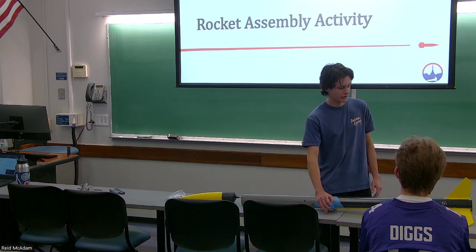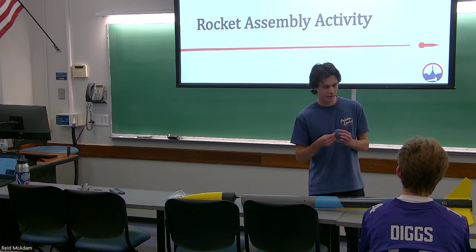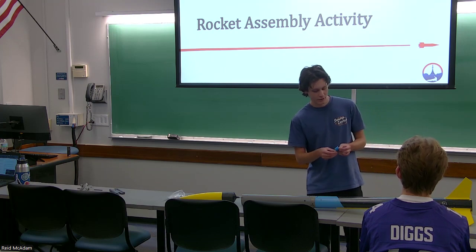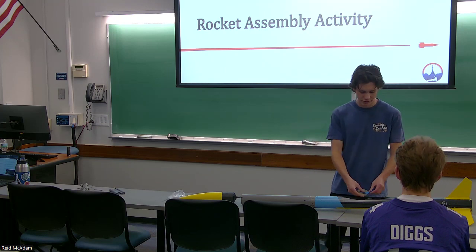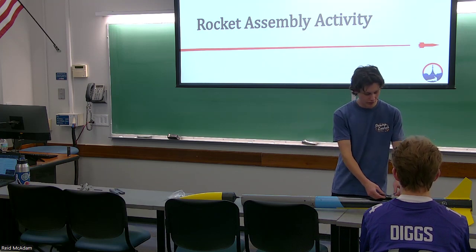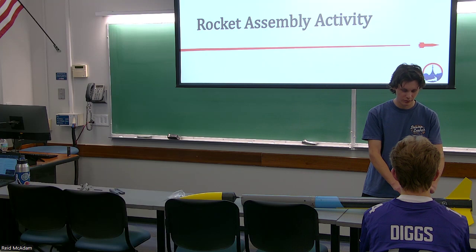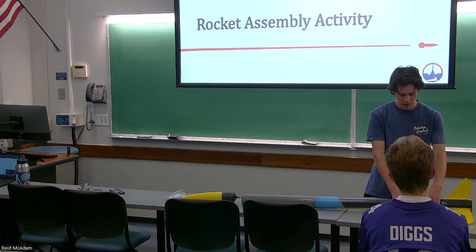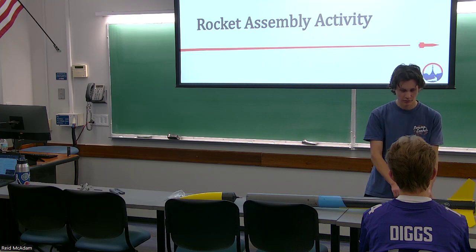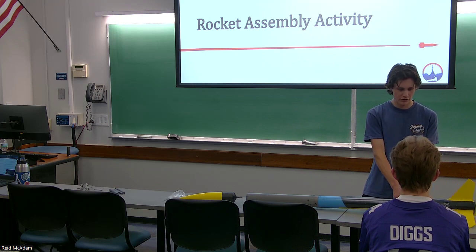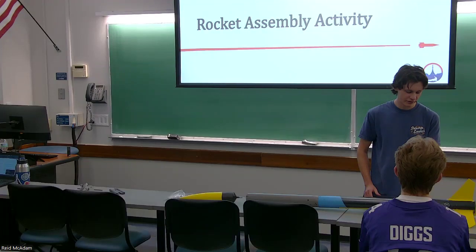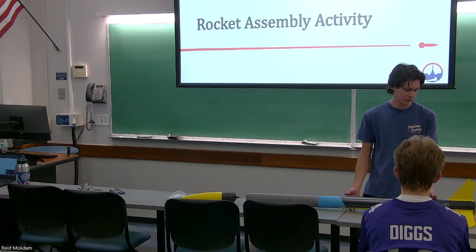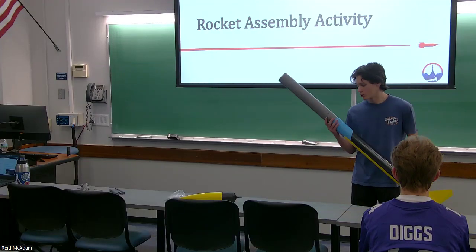I know my stability wasn't as good as my simulations on launch day, because that just happens with manufacturing. Things don't always get built as you predict them to be built. So my center of gravity was a little bit further forward than I thought it would be, but it wasn't so much farther forward that I had to really worry about. So I just rolled with it.